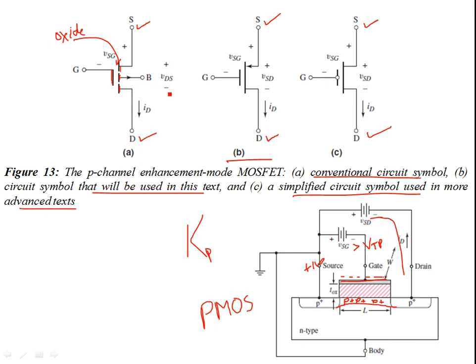The other thing is that this is an N-type. So for PMOS, we have an N-type substrate or semiconductor, and the direction will be from P to N. This is your PN junction. This whole thing is your PN junction, including the reverse-biased PN junctions over here, including the channel and the doped source and drain terminals.